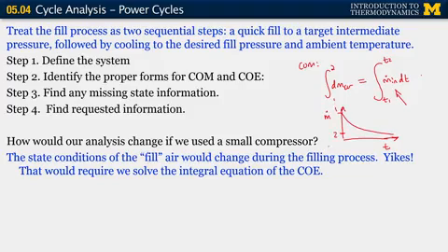And the same type of approximations we were using for the specific heat, when we wanted to invoke assumptions of a constant specific heat, we would consider here. For example, if we're only filling for a very short period of time, maybe I can assume a constant value for the mass flow rate, just an average between this initial T1 and this final T2.